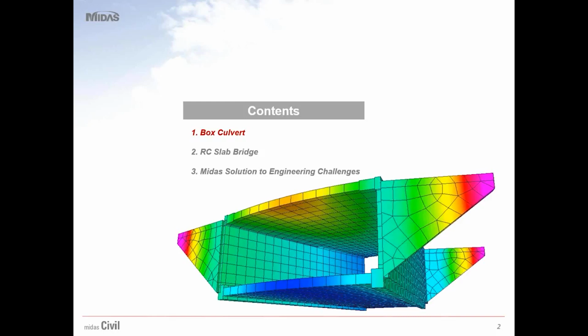When we listen to the word box culvert, the first question that comes to our mind is, why are box culverts so commonly used? The reason is, box culverts are an ideal solution for drainage culverts with wide flow and low hydraulic head. They are very much suitable for difficult site conditions as installation requires minimum elevation and backfill. This is why they are widely used for underpasses, subways, outfalls, bridges, stream culverts, etc.